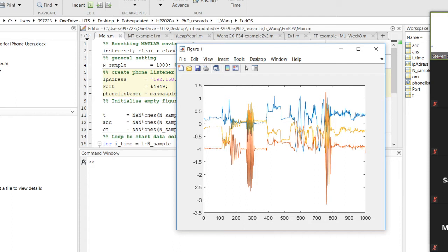They can only do a good estimation for maybe 1 or 2 minutes, or 10 minutes. Especially for position, it's hard. But they can be combined with other sensors. For example, GPS can be combined with IMU, because GPS has no accumulation error. It can determine the location very accurately, and it does not degrade with time.